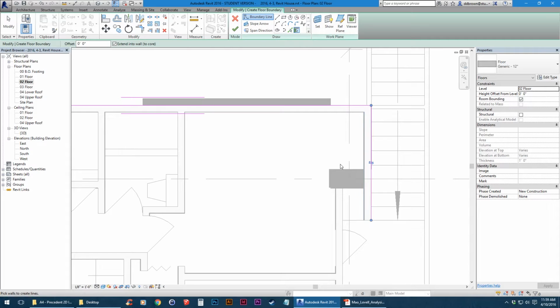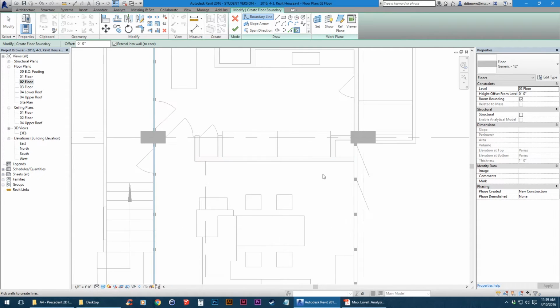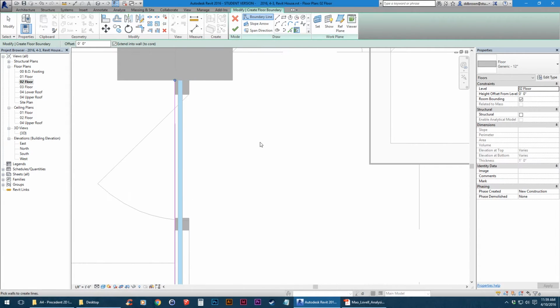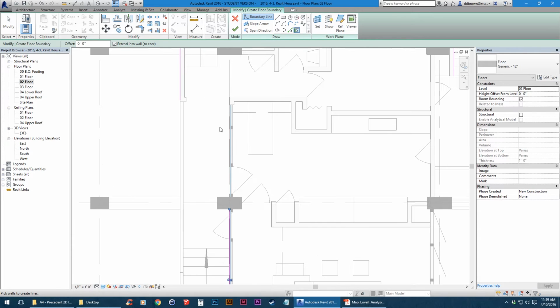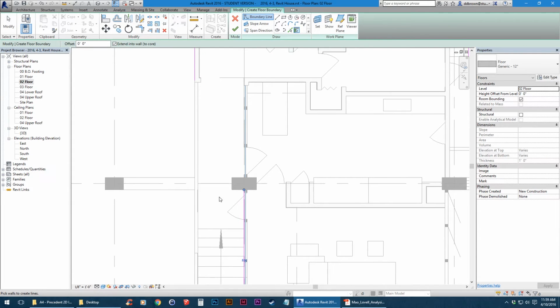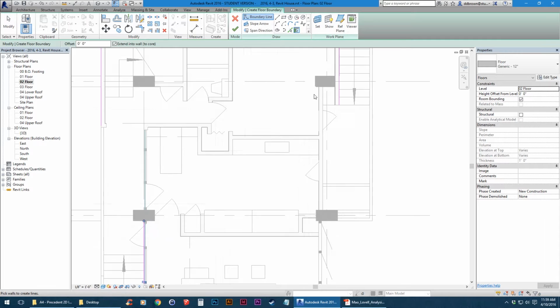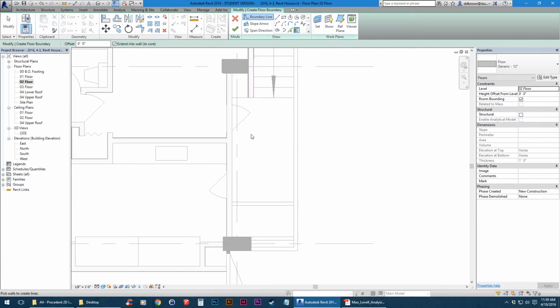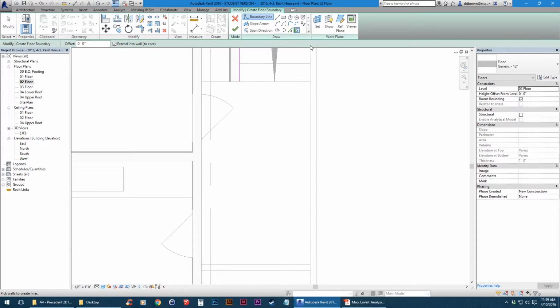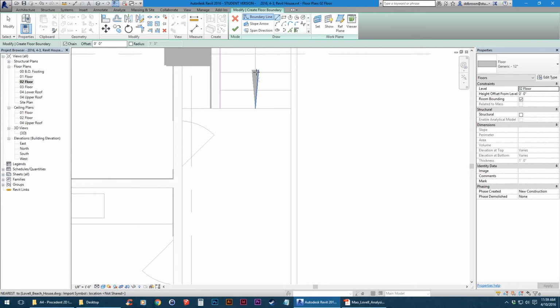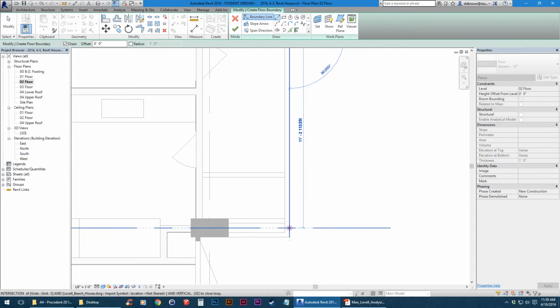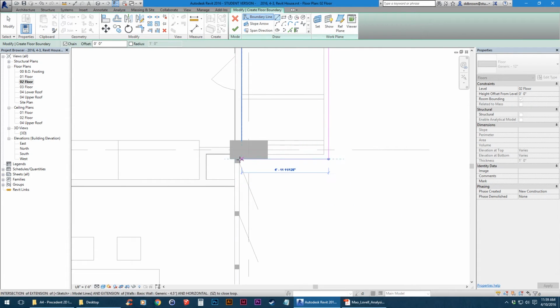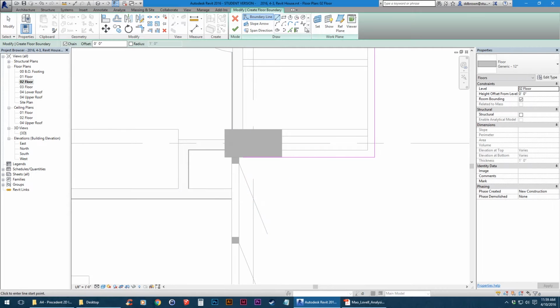So in my instance, only about half of the walls I can choose because for the other ones, there may be some type of gap, or there's a balcony here which I have to manually trace over. You can see that the wall that I could select ends here, and then there will be a balcony right here. So I'm actually going to use maybe just my normal line tool, and I can draw in where that balcony is. And right here we pick up the curtain wall.